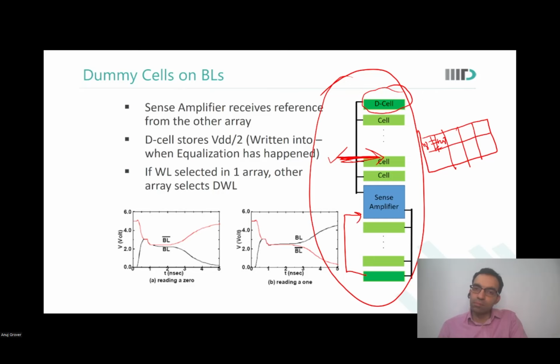In SRAM, bit line precharge and sense amplifier internal node precharge were two different things, sometimes there was a difference. Oh yes, because there was an internal node in the sense amplifier. This sense amplifier doesn't even have an internal node, so there is no question of two different precharges, right?